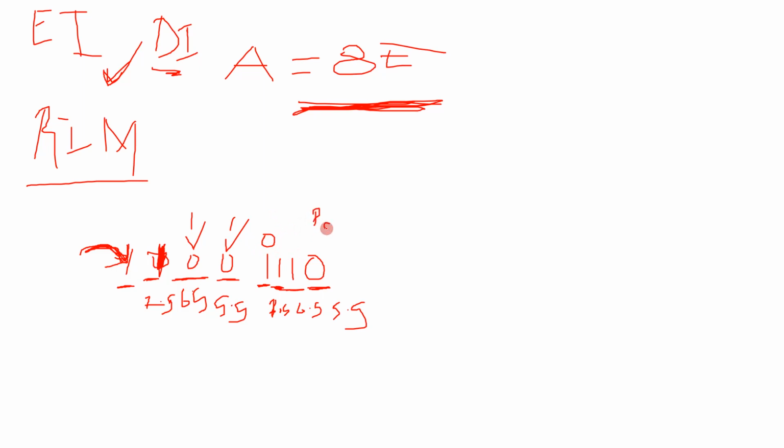This is the D0th bit, D1, D2, D3, D4, D5, D6, D7. Okay, so here 1 indicates that this 7.5 interrupt is being masked off or ignored. Here 1 indicates that 6.5 is being masked off, ignored.